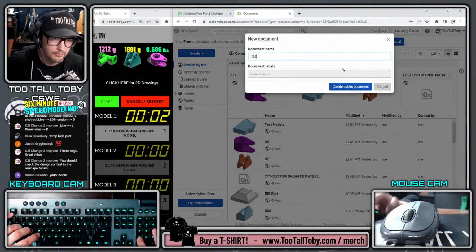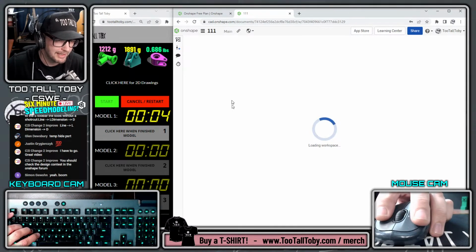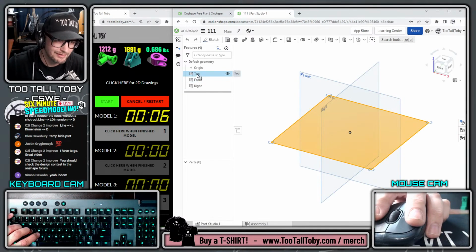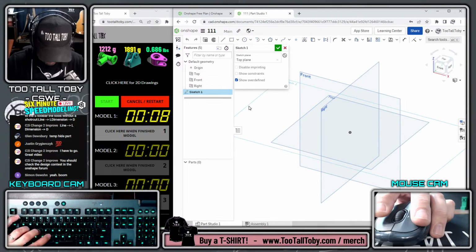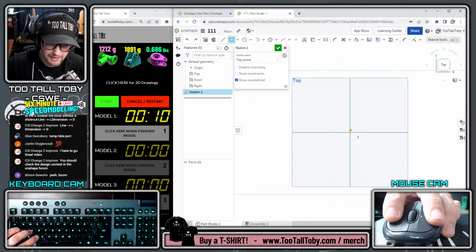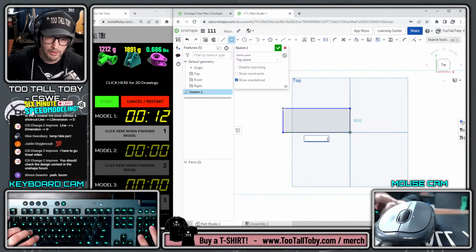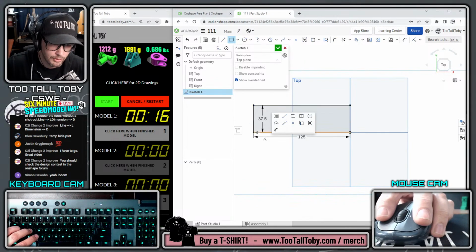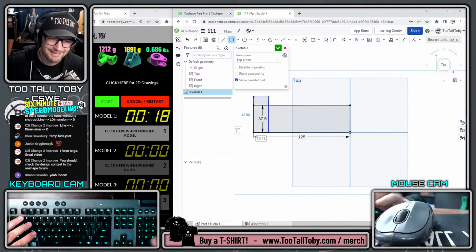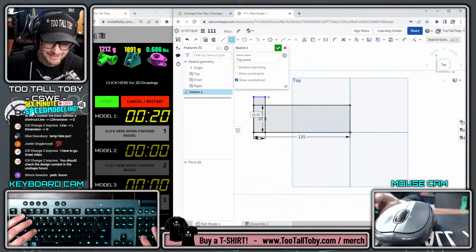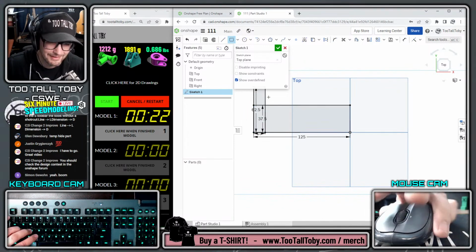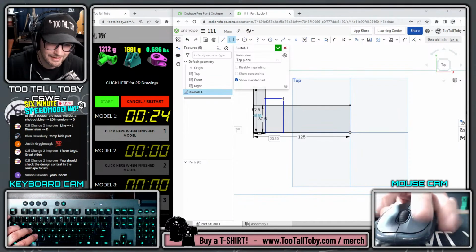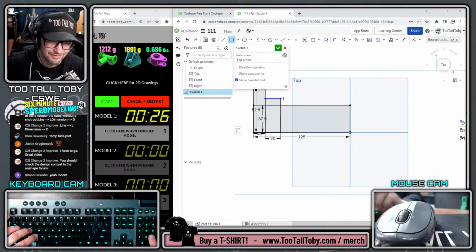Let's go here. This first one, this is our rectangle model, right? We know how to do these. We don't have to be nervous about this one. We know exactly what we're doing. We're going to go rectangle here at 125 by 75 over 2. We're already in the rectangle command, so we don't need to exit it. We're going to make that one 15 by 125 over 2. And we're going to do a final rectangle here at 20 by 50.